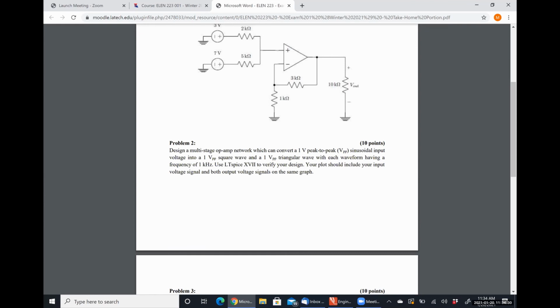Is it correct to use an initial condition? Absolutely. The only way to get around having that would be to put a resistor in parallel with the capacitor in your integrator to effectively make sure that it burns off the energy, but that makes the math way harder. So just set the initial condition to where it starts at 0 energy or something like that, and I'm good. That's much easier to figure out what's going on.